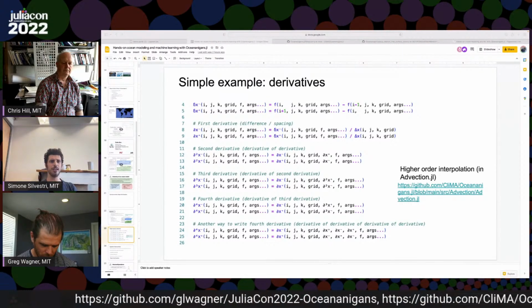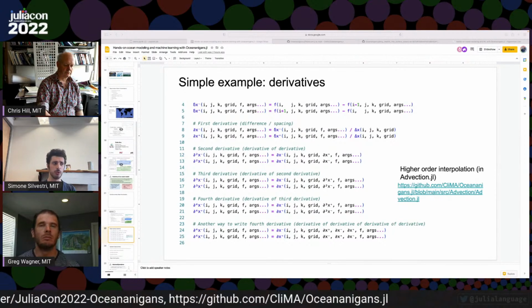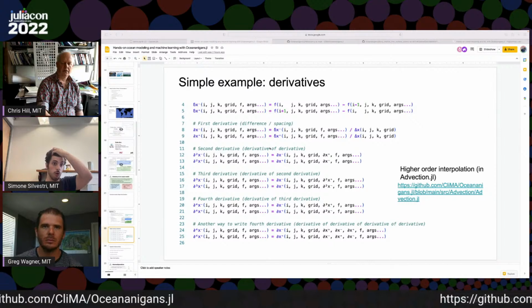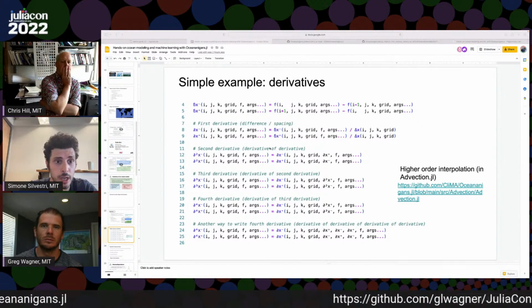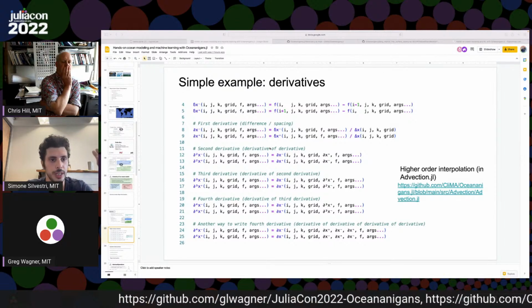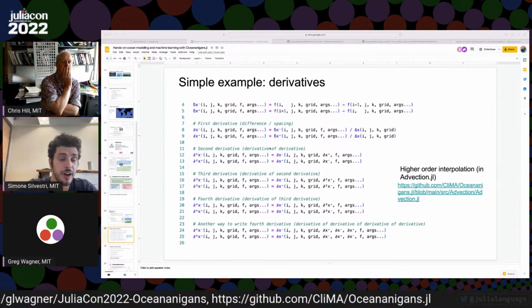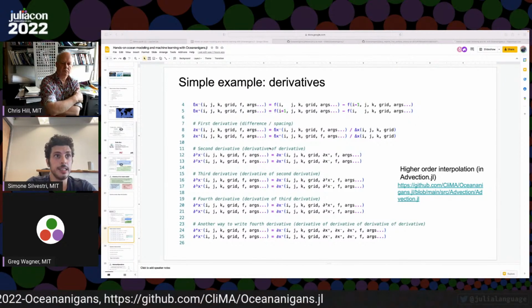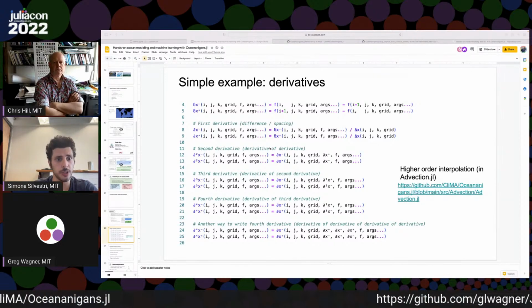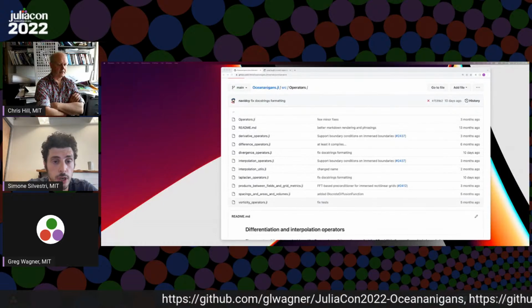So in this way, we didn't explicitly write a for loop over the stencil and sum the whole stencil, but we composed the function starting from very simple building blocks. And this is the way the whole of Oceananigans works. Everything which is not global computation, for which we need actual solvers, Chris will talk about it later, is defined as a function of ijk, and if it can be constructed by simpler functions, it is always constructed as a composition of operations. So just to give an example, let's go see a little bit of the code.